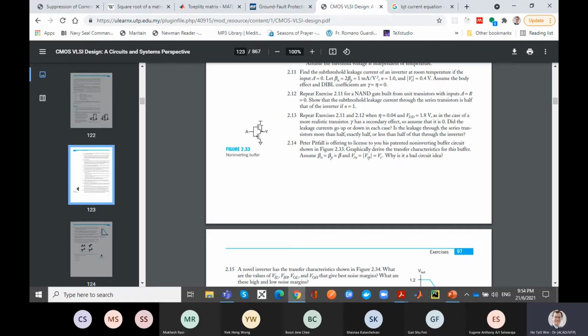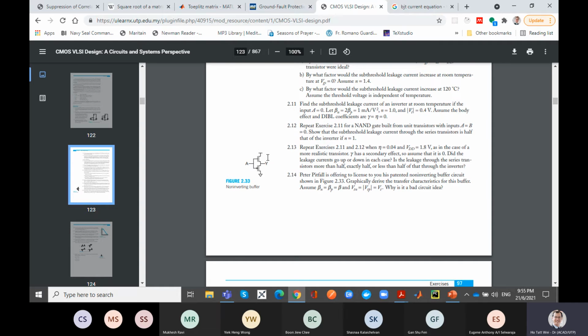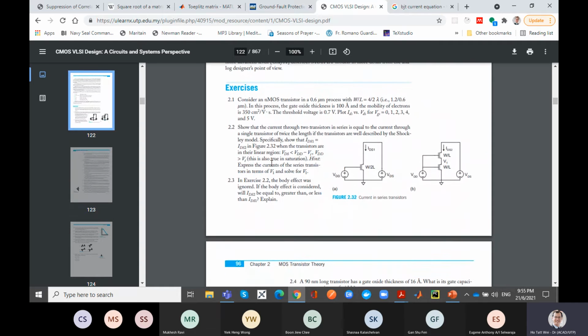As this goes up to logic 1 because it is charging through this path, the VGS is reducing and reducing. As the VGS reduces, the channel here is going to be less and less. So it's like you're trying to pull it up, but at the same time you're reducing the amount of current. It goes up very fast first, then slows down, and at some point gets very, very slow before it reaches logic 1. So this is called weak pull-up. Why? Because your VGS is changing as you are changing the node. So this is not great as a gate because it's slow.